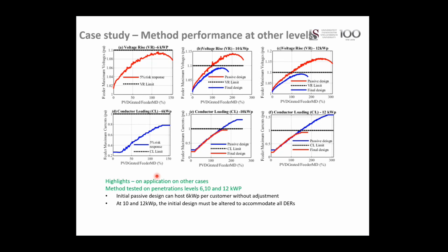No, I didn't. It's a bit of a mind shift. Maybe you can try again. Okay. Wayne or Solani, yes? Okay. I think what Solani and Marcus meant by lightly loaded is when your customers that only draw load and don't generate are at their lowest, and your generation is at the highest, then you get the biggest voltage rise.